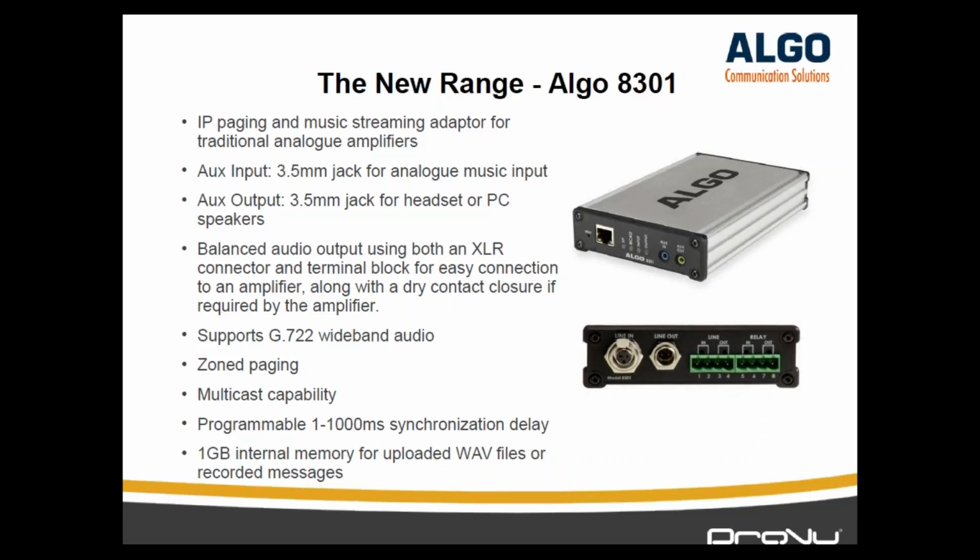It is sort of an ATA in some certain aspects, but it is much more powerful because with an ATA, and we'll discuss that later, you can't actually control the music or the PA system. All you're doing is just making an announcement, and then the ATA will obviously convert it into SIP and then plays out. But with this thing, you actually control the audio that goes to the amplifier as well. So including Algo H301, it effectively becomes your main control system for the amplifier, and you can control which audio stream to play where.